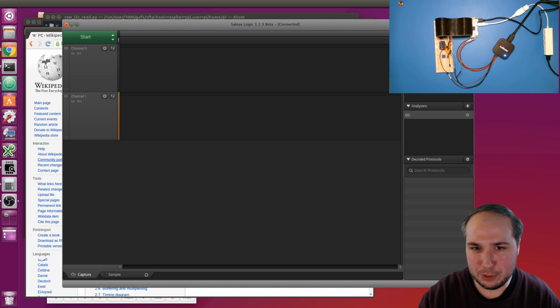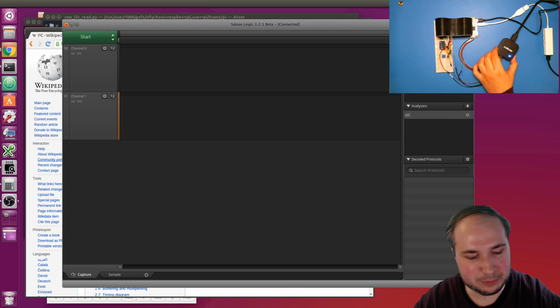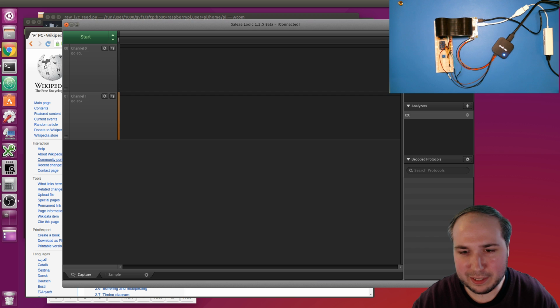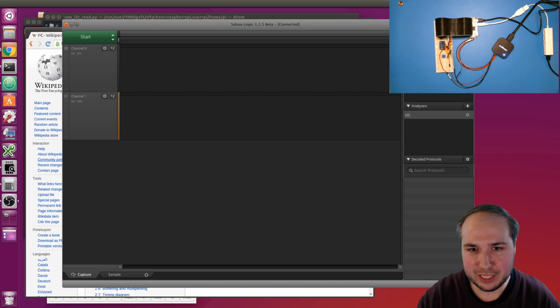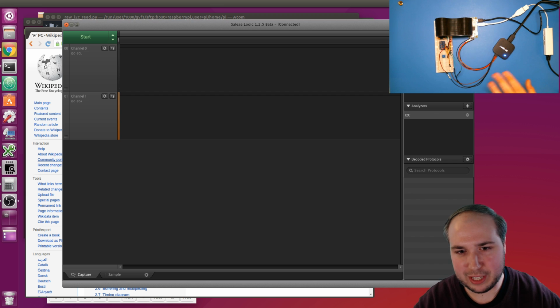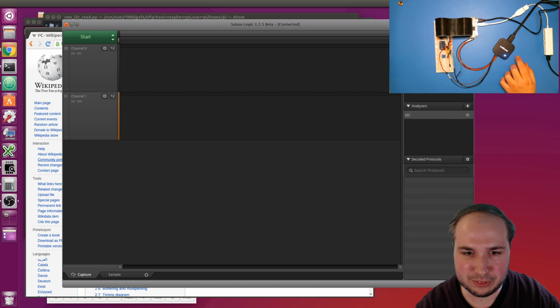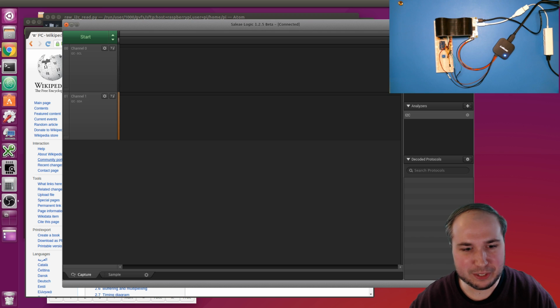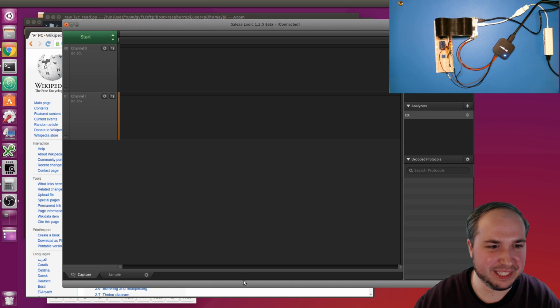If you're working with new hardware and maybe writing a library to talk to a device that you haven't used before, then you would definitely benefit from a logic analyzer like this one. So definitely think about it. I like it because the software is pretty easy to use. It's cross-platform, and it's relatively inexpensive. I think this one's about $500, but a base 8-channel one is about $200 or so, which in the grand scheme of test equipment is pretty inexpensive, unfortunately.